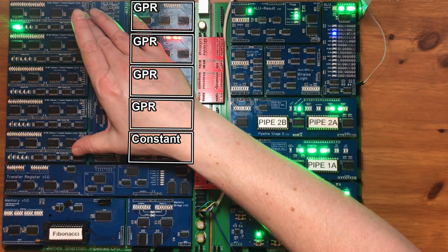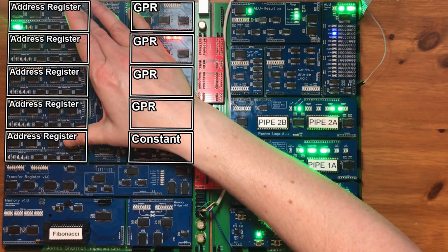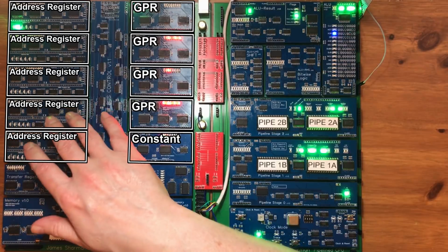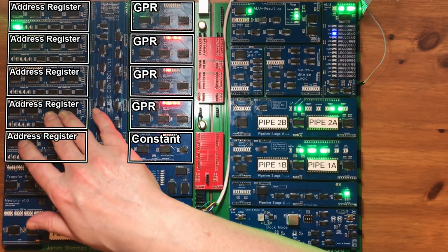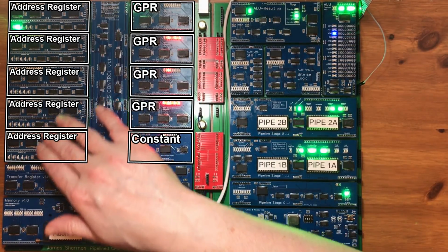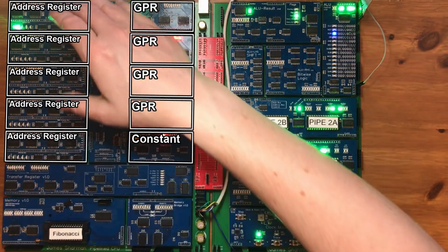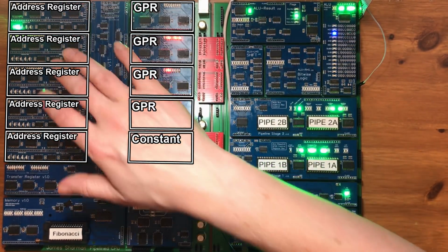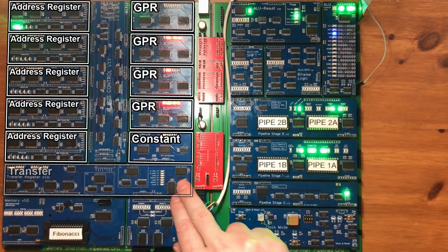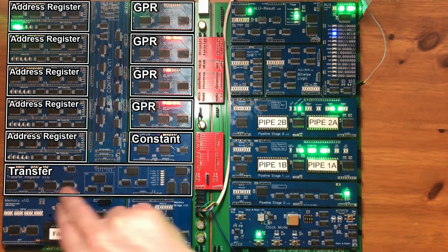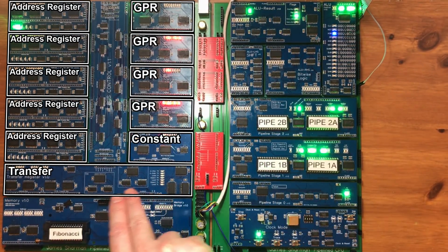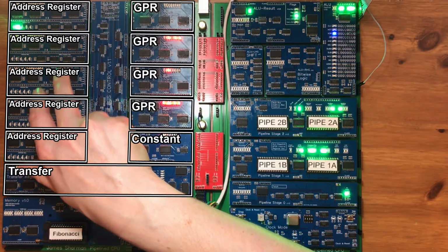The 16-bit registers are over here, and I call those counter address registers. There's 5 of those, and they're all identical. They can increment and decrement, and they can load from a bus I call the transfer bus, assert back to it, or they can push their value out onto the address bus. So the address registers are all 16 bits, giving me a 16-bit address space. Along the bottom here is a register I call the transfer register, and this bridges the 16-bit side and the 8-bit side by having 2 8-bit registers that also present as a 16-bit register.